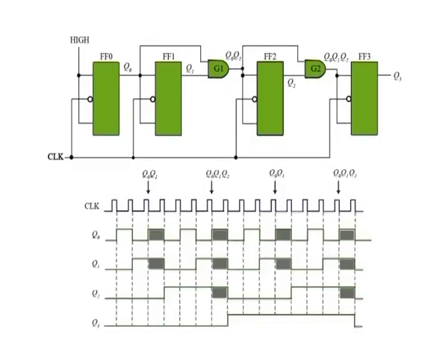Figure shows a 4-bit synchronous binary counter and its timing diagram. This particular counter is implemented with negative edge triggered flip-flops. The reasoning behind the J and K input control for the first 3 flip-flops is the same as previously discussed for the 3-bit counter. The 4th state, flip-flop 3, changes only twice in the sequence.